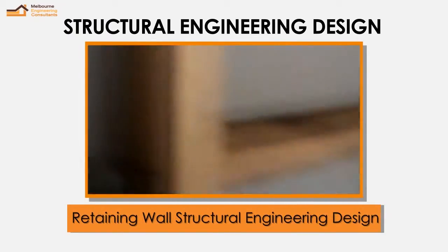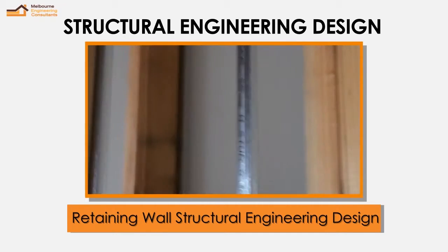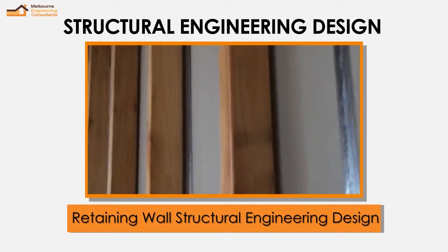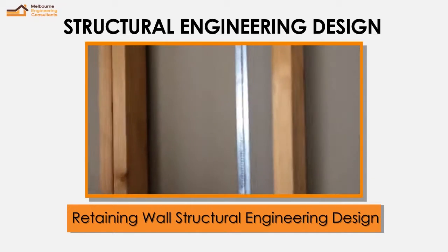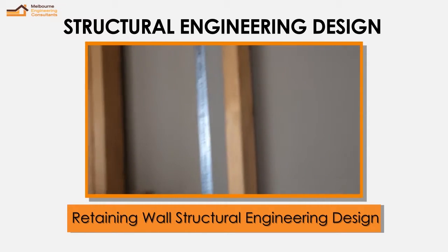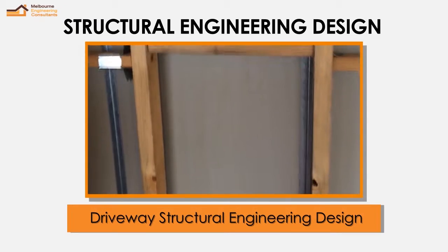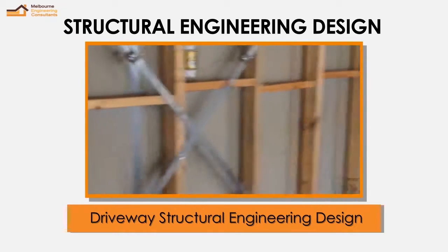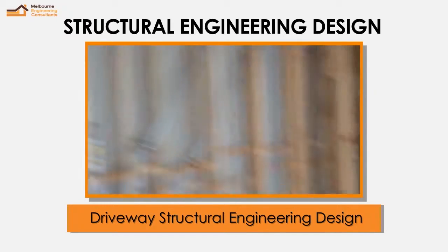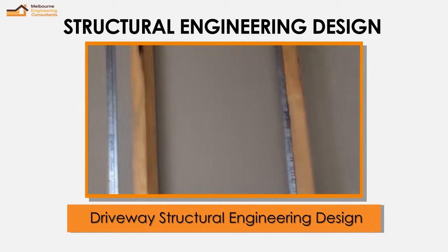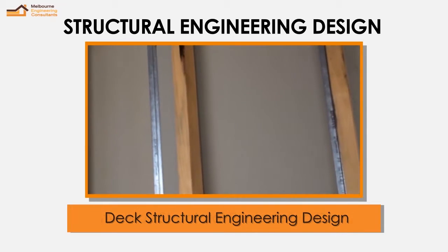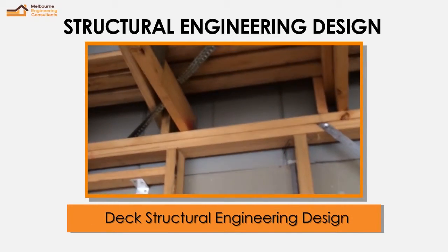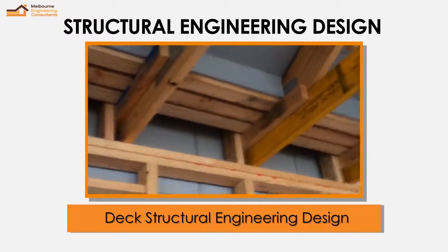This wall is my party wall. So we have one 90mm stud wall this side, shaft liner in the middle for the sound insulation and the fire protection, and the other side we have another timber stud wall, which is my load bearing wall. So half of the trusses is coming on this one, and half of the other side of the roof trusses will be coming on the other side. It's like a more fireproof and more sound insulation wall with the shaft liner in.